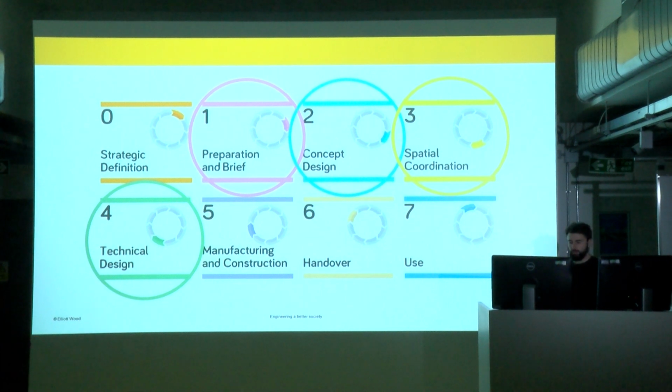And in that process, we can see how the embodied carbon value changes for our structures or our buildings, because we're getting into more detail. As we get down the RIBA stages, you can see it slowly increases in most cases with our projects. And that's not unsurprising because finer details are coming together and so on. That's when typically we would stop using the tool because the project's handed over onto site for construction.